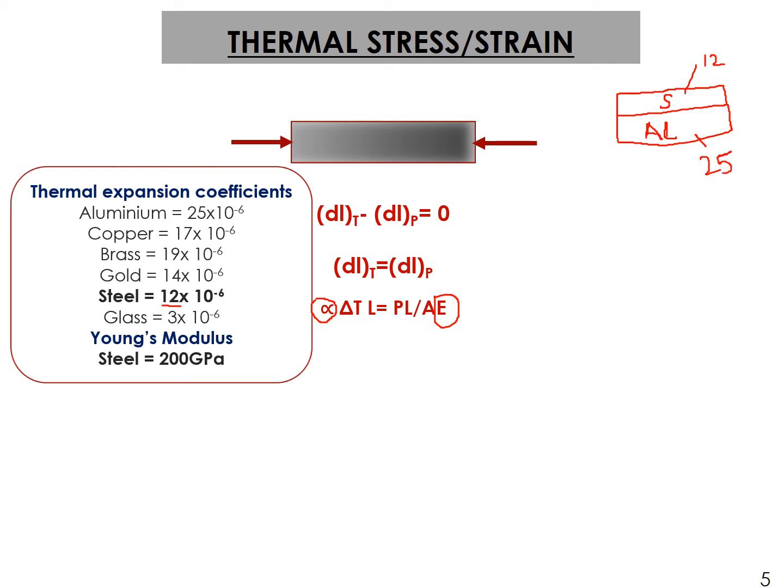Yes, the steel will restrict the expansion of aluminium because of its lower thermal expansion coefficient, and we can come to an equilibrium state. This is just to give you an idea that we do develop composites with different expansion coefficients. Again, we have to make certain calculations so that we come to the exact value. That is the practical significance of these coefficients.